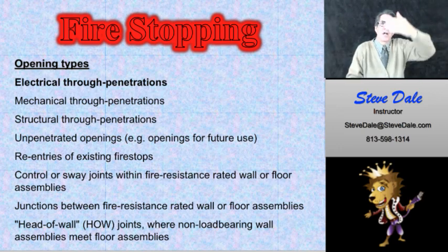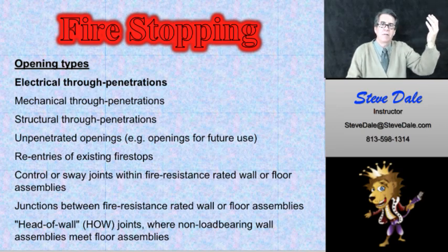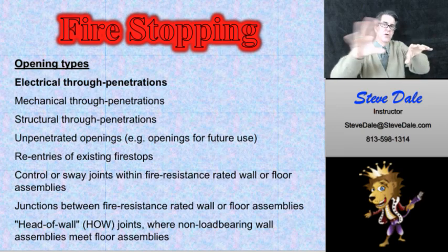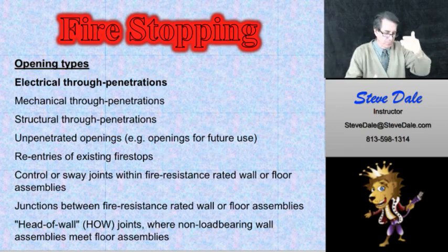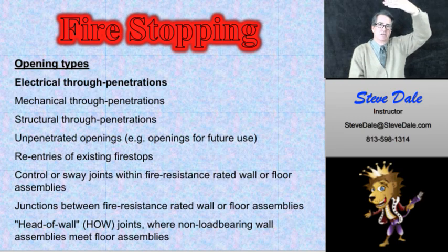So you have a fire stop there, and these fire stops are rated. A standard drywall fire stop can be a 2-hour rating. That's a standard one in a strip mall between the units. You'll have a firewall that goes from the very ground floor all the way up to the roof, and sealed.